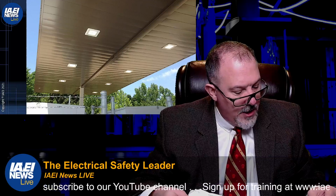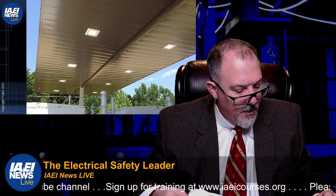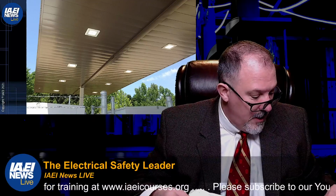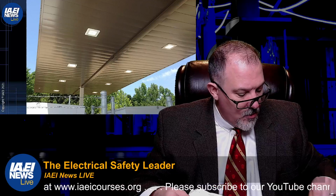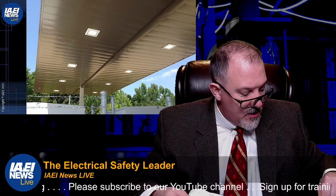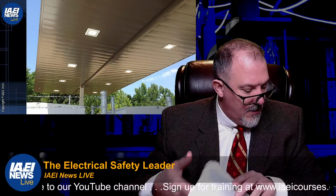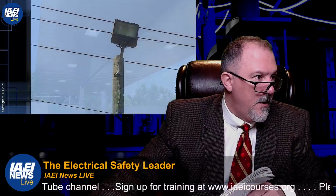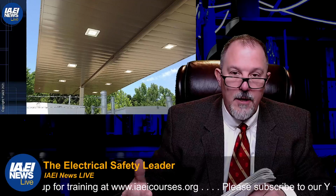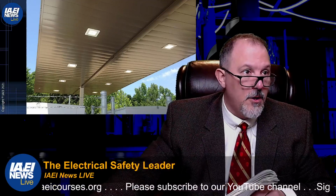A damp location is protected from weather and not subject to saturation with water or other liquids, but subject to moderate degrees of moisture. This would be a damp location. A wet location is an installation underground or in concrete slabs or masonry in direct contact with the earth, or in locations subject to saturation with water or other liquids, such as vehicle washing areas, right? So that is definitely a wet location. This is a damp location. You need to buy and install the right luminaires for each of those locations.